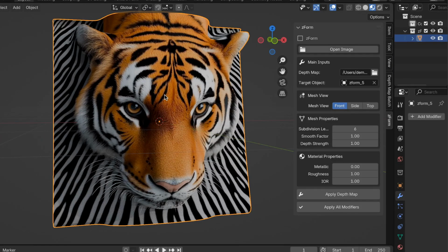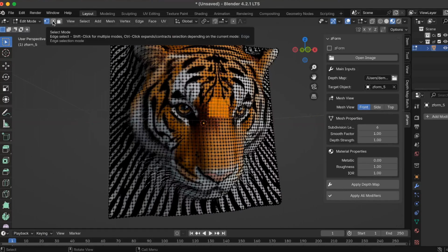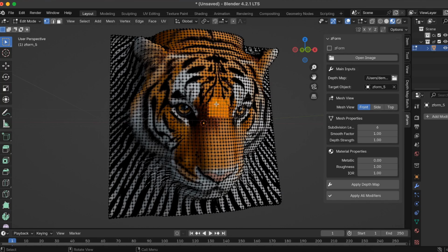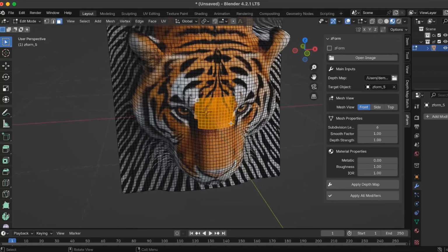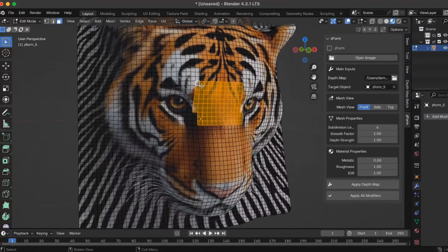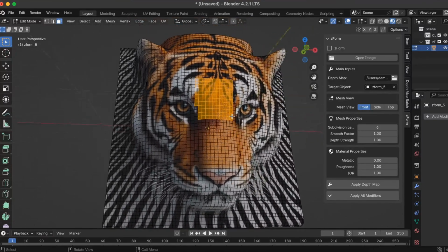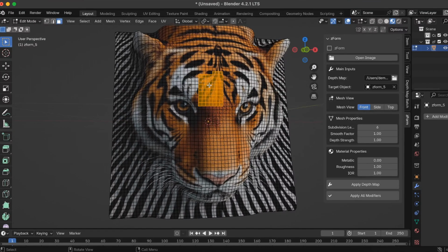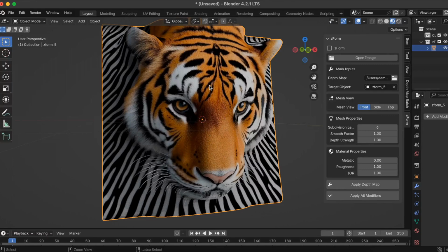Let's go into edit mode by clicking Tab on your computer. In the top left, there'll be 3 different options to select vertices, edges, or faces. So right now I'm in vertices. You can see the little points. If I wanted to go into face mode, I'd click on the faces, and you'll select faces. For the most part, it's pretty clean topology. That being said, I've never tested this with other software like 3D Studio Max, but it looks pretty clean. I've also never tested this for 3D printing. To get out of edit mode, all you need to do is press Tab again.